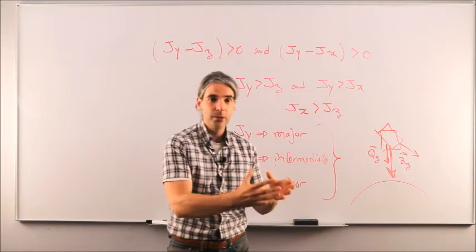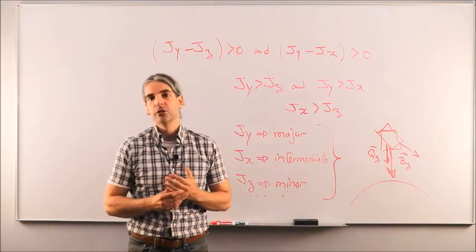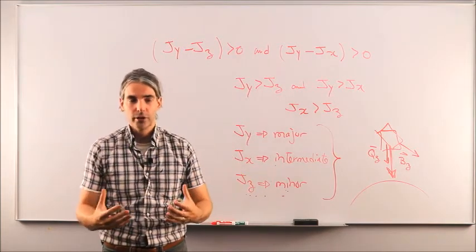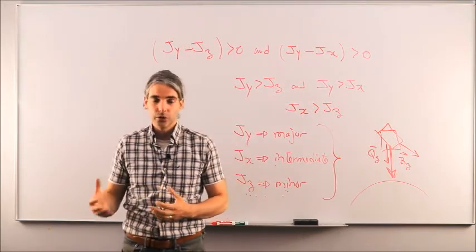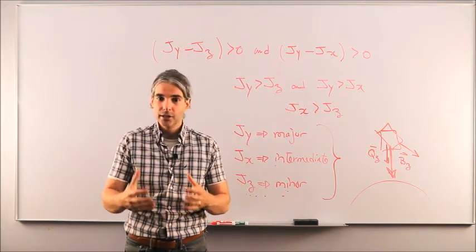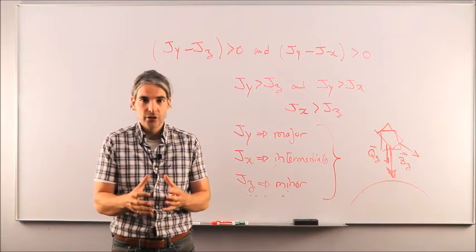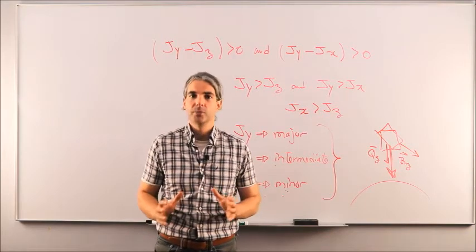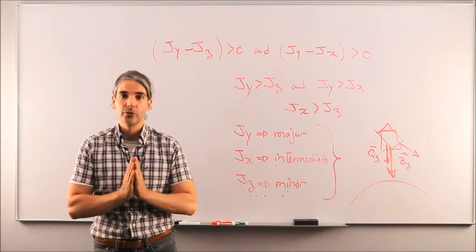So if you want finer pointing accuracy, you need to turn to active feedback control system techniques and employ actuators on board, small thrusters, reaction wheels, control moment gyroscopes that will torque the spacecraft in real time in an active way to always make small corrections, to always fight any perturbations that are trying to push the spacecraft around. And that, ladies and gentlemen, will be the bulk of Chapter 5, okay?